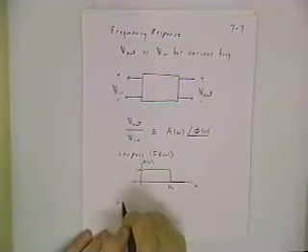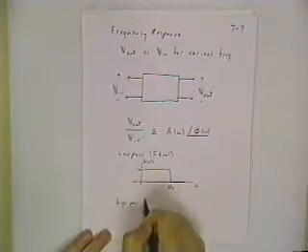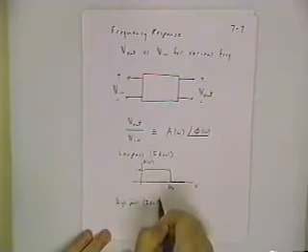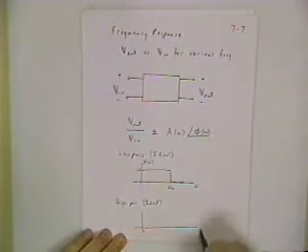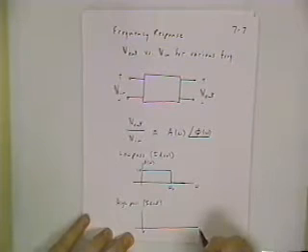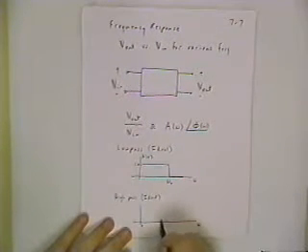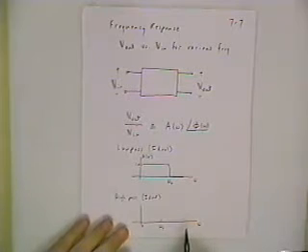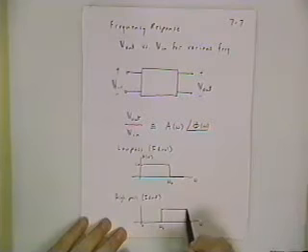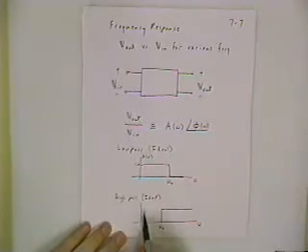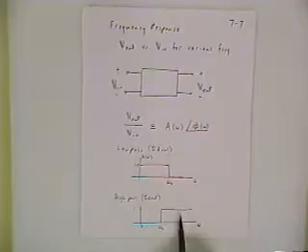And likewise for a high pass, at least ideally, would look like this. Starting off with frequency of 0, going up to higher and higher values. At some intermediate frequency omega naught, above that frequency you would pass all signals, and below that frequency you would block. So this is the value of 1.0. And keep these ideal pictures in mind when we talk about the actual first order filters made out of resistors, capacitors, and inductors.